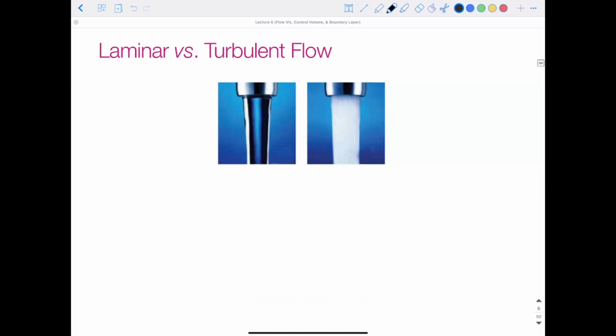So next up is laminar versus turbulent flow. These are two very highly talked about. You've probably heard about these before this course even, the difference between laminar and turbulent. So the definition here, laminar flow is highly ordered and very organized flow in which fluid layers shear on each other. And highly viscous fluids such as oils flowing in small pipes or narrow passages are typically considered or most often laminar type of flows.